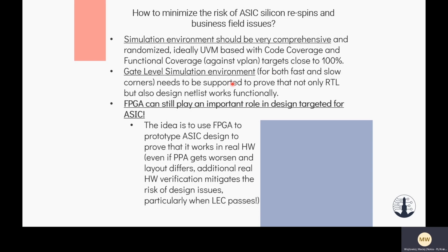And the third point I think is very interesting, because in verification of an ASIC design, FPGA can still play an important role in prototyping. Think about this. We start an ASIC project and have 2 years for the first shuttle. So the first 2 years are for development. Apart from verifying with those 2 techniques in the very beginning, for iteratively changing the design and getting new features, we can implement some initial versions, with not all the features, in FPGA and just make sure that it is working in real hardware.